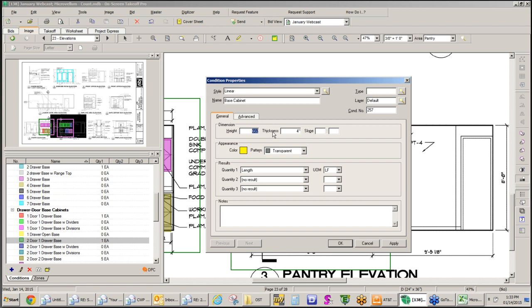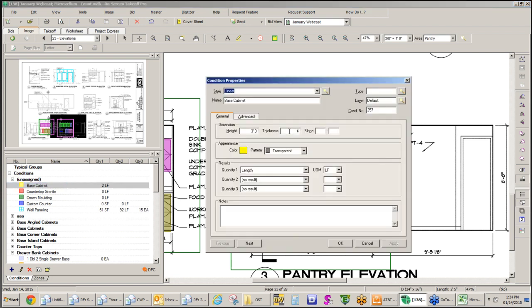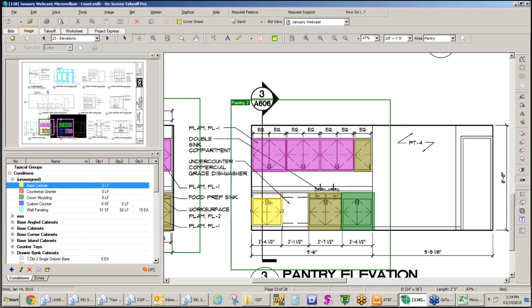Make sure that I do this correctly. I don't care about the precision of it right at the moment, but we'll do a takeoff in a second. You'll see what I'm doing. Instead of just selecting an item that might have an arbitrary size, I could literally be doing a takeoff to calculate its width. So if we looked at this again and said, I want to make this display as 2 feet, for example, you would see that that's what it does. And if I change the amount that I pulled or pushed this, it's then calculating the actual lineal feet for this.